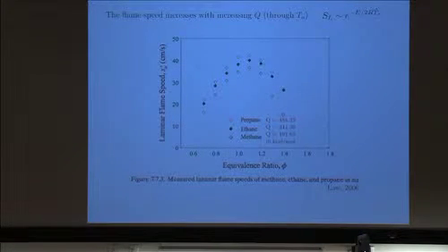And this you can see, for example, in this graph. You have three flames: propane, ethane, and methane. This is the dependence of the flame speed on equivalence ratio, which will have more or less a similar behavior to the flame temperature. In other words, it peaks near stoichiometry, and it's smaller on the lean and rich sides. But this is not what I want to show you in this picture.